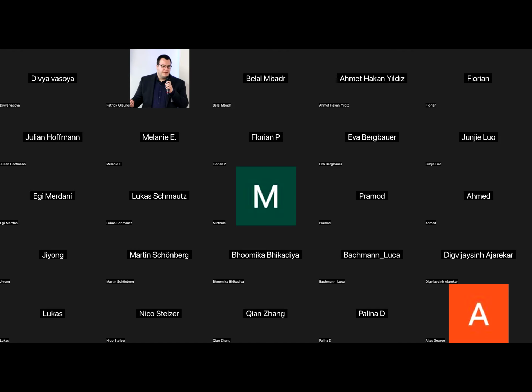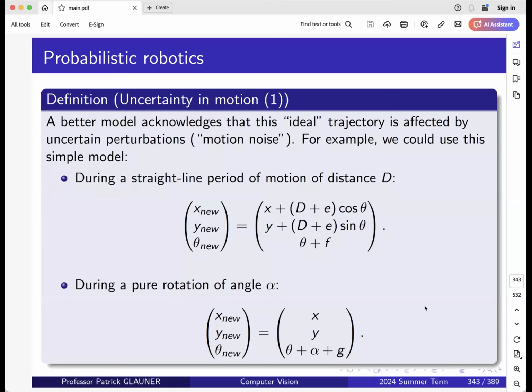And then maybe depending on the environment where you put your robot, this will again vary. Maybe on certain floors or on a certain surface, it will move better than on a different one. How to measure this exactly is something we will see, but it's certainly something you need to bear in mind, that there's always some error in the distance as well as in the rotation.